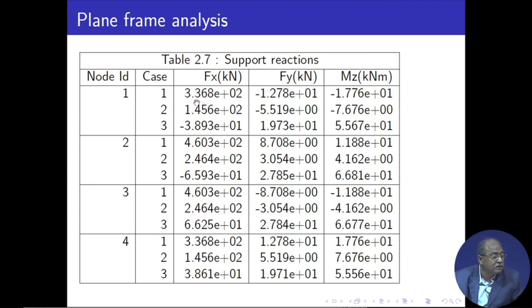That means 336, 145, 460, 246, 460, 246, 336, 145, all of them, that if you add dead load and live load, that one should match, and it matches. Similarly, for the lateral load, you see that it is not Fx, the load applied in the x direction, this is the one, that y, that one in the column, because it is in the local coordinate system. So, that is why if you add this value, this value, this value and this value, then you should get whatever lateral force you have got, that Vb, it should match with that, and it matches. So, that is the one actually you should find out, that particular value that you should check.